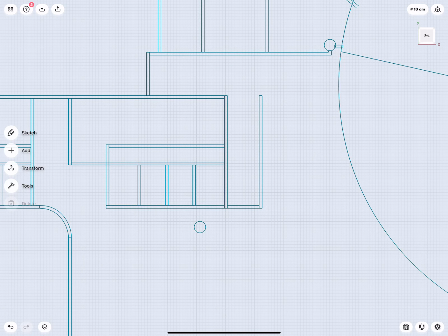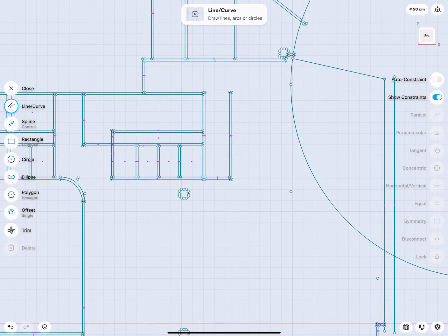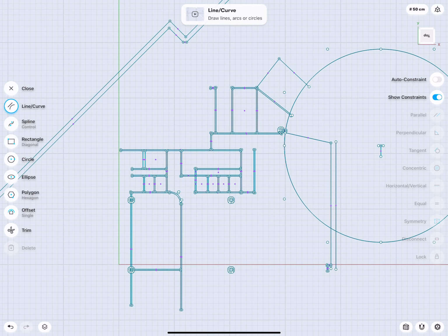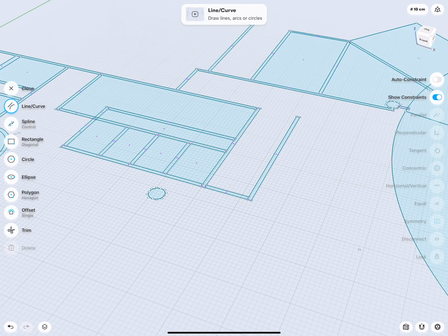There are various strategies for how we could create such a new floor plan. In this case, as you can see here, I just drew squares representing the interior walls, and they were all butted up next to each other. This was very fast, very effective, and when we go into a perspective view, you start seeing that closed shapes are all being filled.